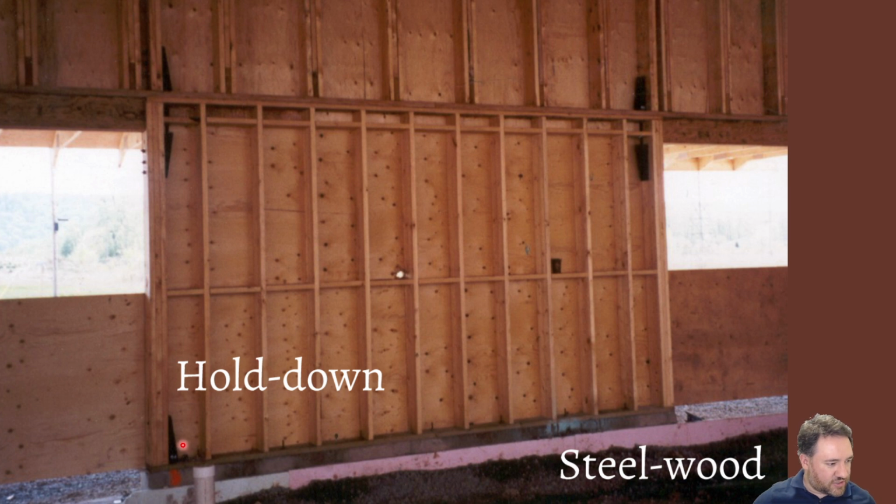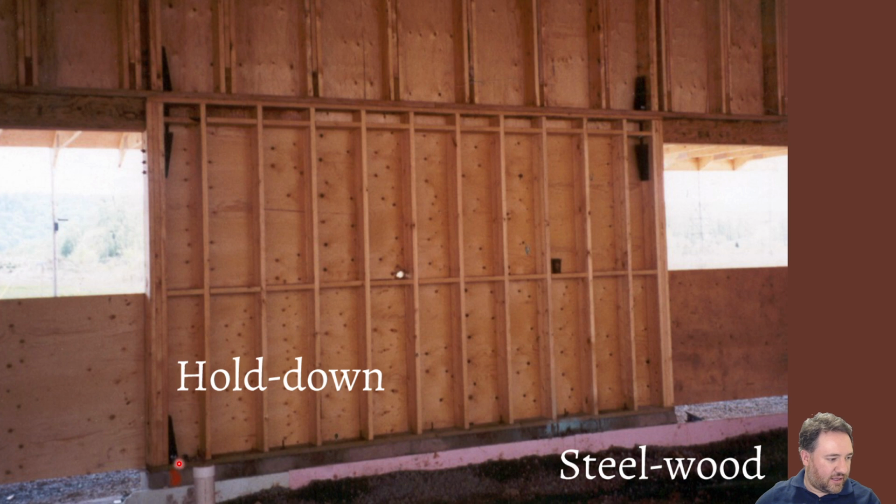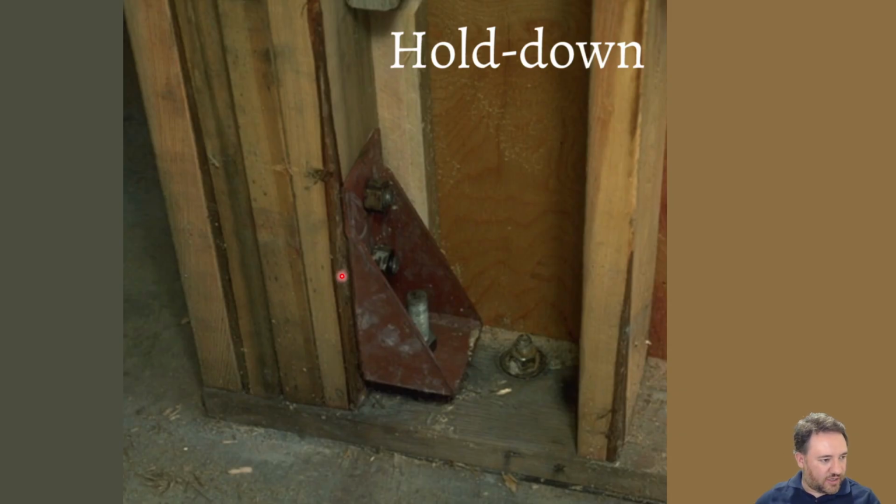But before I get to that close-up, you can see for light frame shear walls, as we talked about before, we need to have hold downs. The hold downs keep the wall from rocking. Because if I have my wall here and I push on the wall, it's going to want to rock up. So I have to hold it down at both opposite corners. And so I can use a bracket, and then the bracket will be connected to the foundation at the bottom. Or in upper levels, you'll see that we connect one bracket on one floor to an identical bracket on the next floor. And it might look something like this.